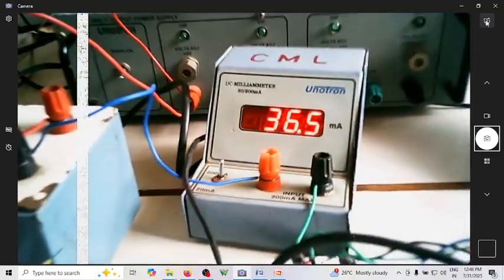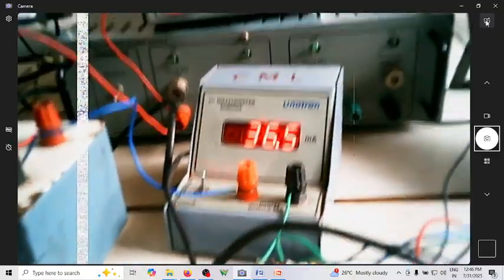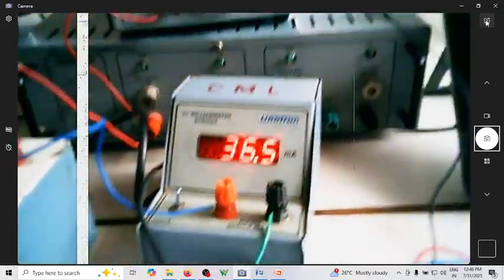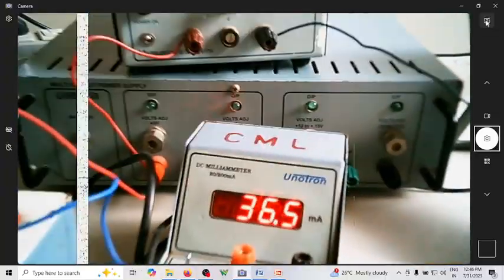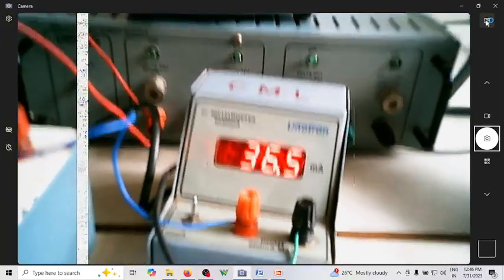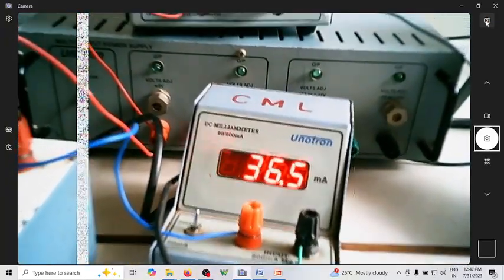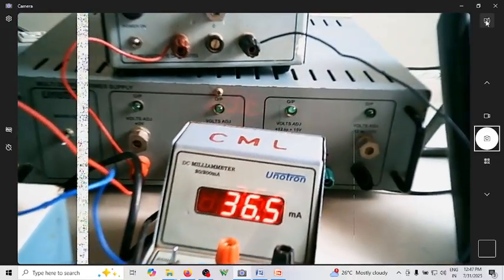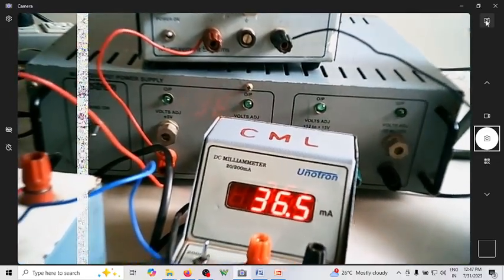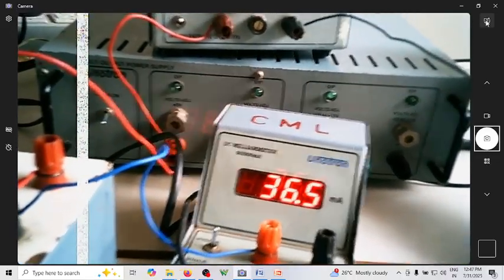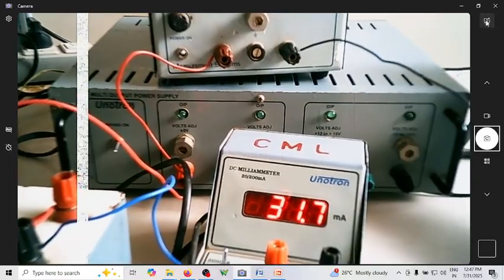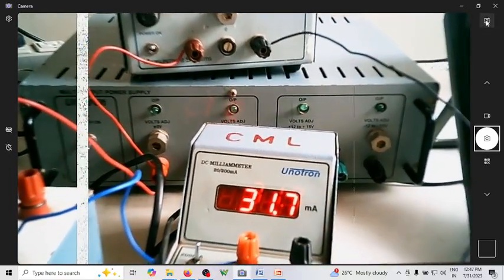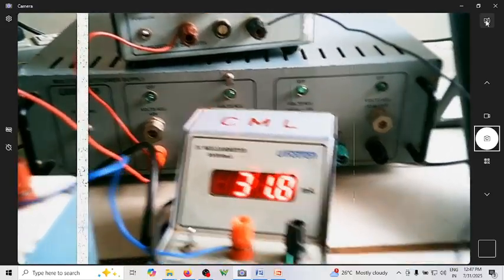So this is the way we have to understand. There is a minimum current of 35 milliamperes and above that should flow through the coil so that it makes contact. The common is now connected to NO. If you reduce the current by increasing the resistance, you can see it's open. So where is the common now? Common is now connected to NC.